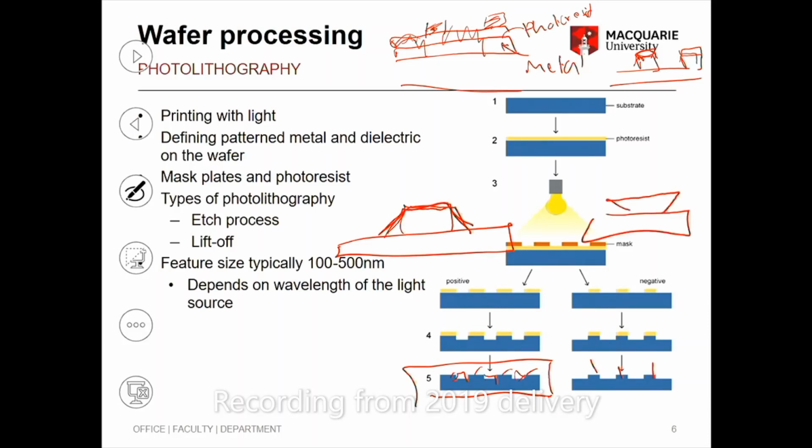Also, there's a certain width you can go with this metal. So usually it's about 5 micrometers width. That's what the layout manual says: the minimum width you can do is like 5 micrometers. You need to make sure your tracks, when you do your layout, are at least 5 micrometers or more.